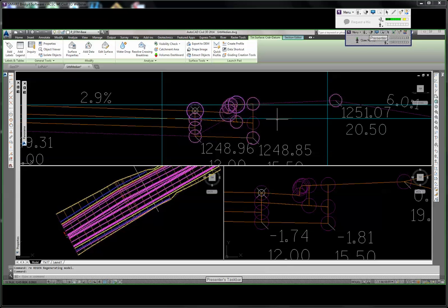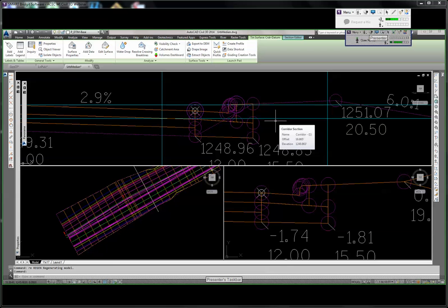So what we're going to do there is kind of trick it into giving us the surface that we want. What I'm going to do is place in a generic link and then give that generic link a certain code so it will respond appropriately with the surfaces. Now there's a couple different ways to do this, a couple different schools of thought on this. One of the ways that you could do this is put the generic link here and going outward. Now the amount out is going to be very, very small. In fact, so small you can't see it. It should be 0.01. I'm an extremist. I'll go 0.001. So it's very, very small. No one could ever see that it's there, but that's enough for Civil 3D to make the difference.